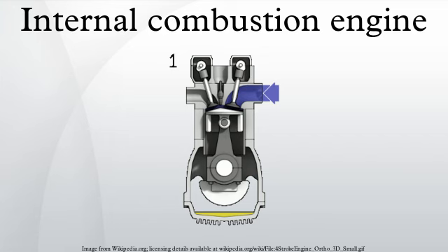In some engines, especially for turbine engine blade cooling and liquid rocket engine cooling, fuel is used as a coolant, simultaneously preheating the fuel before injecting it into a combustion chamber. Engine starting. An internal combustion engine is not usually self-starting, so an auxiliary machine is required to start it. Many different systems have been used in the past, but modern engines are usually started by an electric motor in the small and medium sizes or by compressed air in the large sizes.